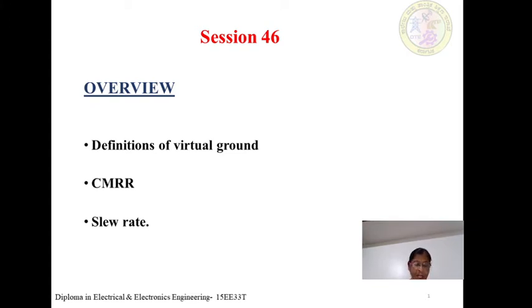When the input signals to a differential amplifier are in phase, meaning whatever signals are given to the inputs V1 and V2 should be in phase, not out of phase, and exactly equal in amplitude, they are called common mode signals.